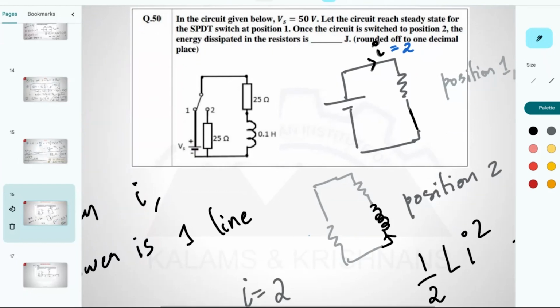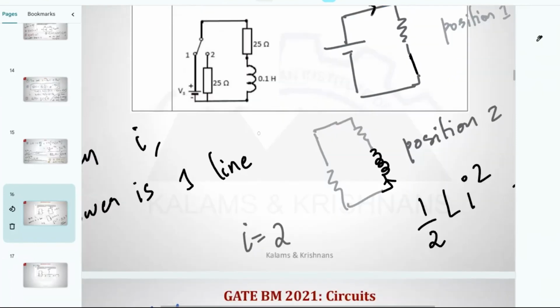What you have here is a circuit without a voltage source, right? That voltage source is removed because the switch moves here. We have essentially a resistor-inductor-resistor circuit, an LR circuit. Quick way to look at it: whatever energy is there, there is some energy in the inductor, and it eventually gets dissipated by the resistors. So initially, say this is like for salaried people, they get a monthly salary. Over the course of the month, expenses kind of eat away all the salary, right? This initial energy is this current in this inductor.